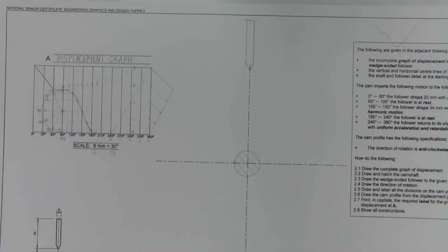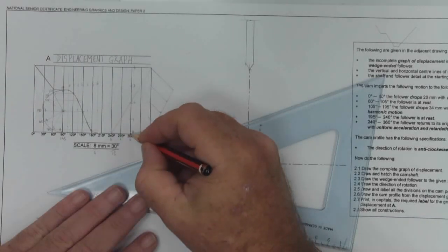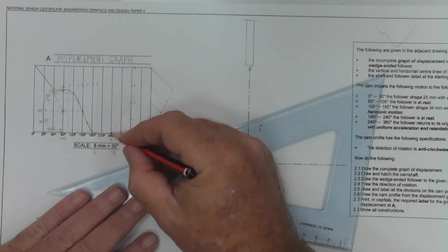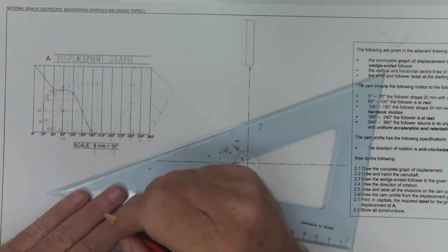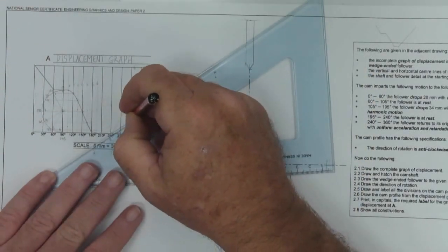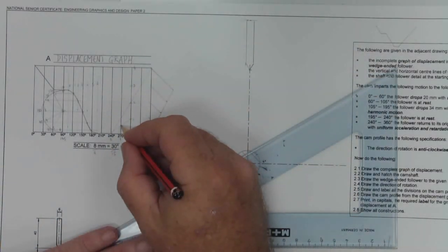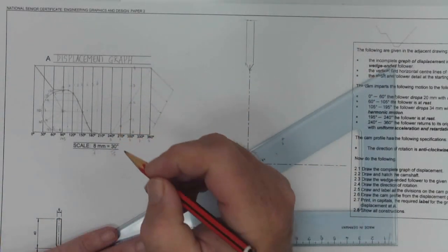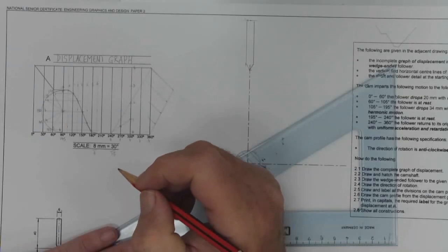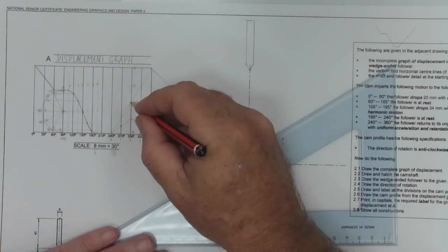And now we do a bit of a matchup. So if I take height 0 to this corner here, that gives me my start point. Now if I go from my corner to height 1, where it intersects the vertical line 1, gives me my point. Now point 2 we've already got because it's the center one.